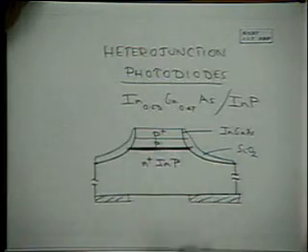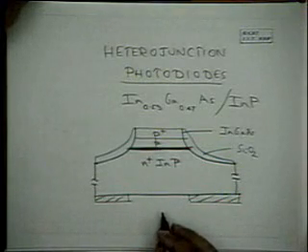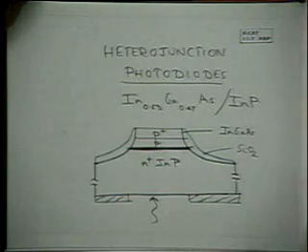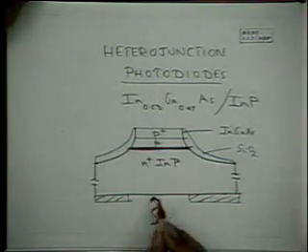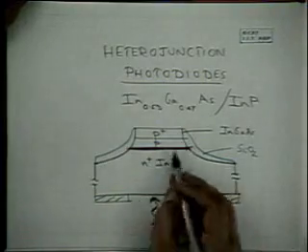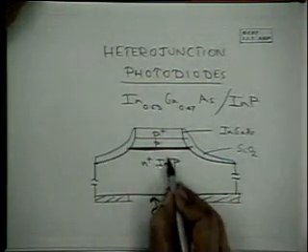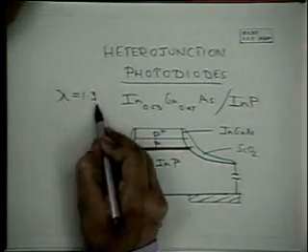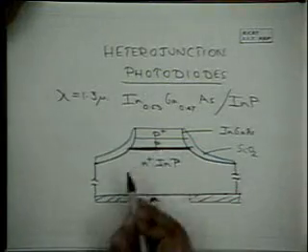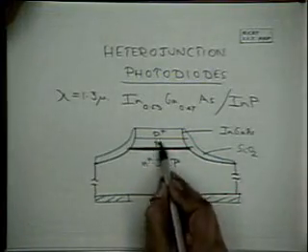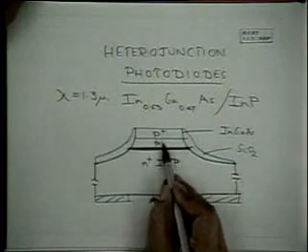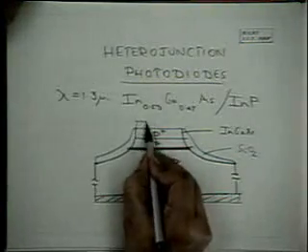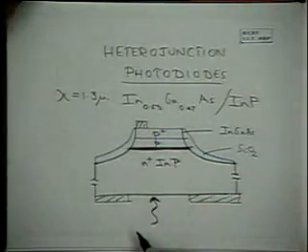This is an annular circular metallic contact, and the light enters indium phosphide. Indium phosphide is completely transparent at 1.3 or 1.5 microns. Light enters here, and notice here this P is substituting for the I. It's a PIN diode, but you're not getting an intrinsic layer, it's a P layer, and we have another metal contact here.